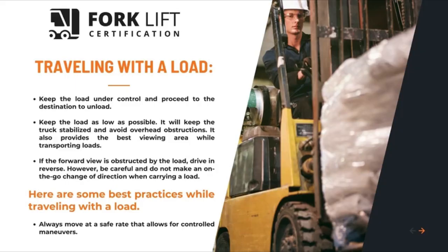If the forward view is obstructed by the load, drive in reverse. However, be careful and do not make an on-the-go change of direction when carrying a load. Here are some best practices while traveling with a load.